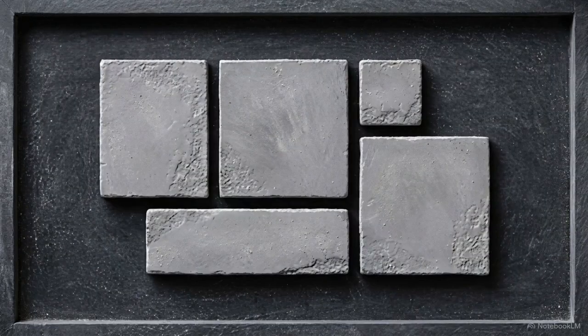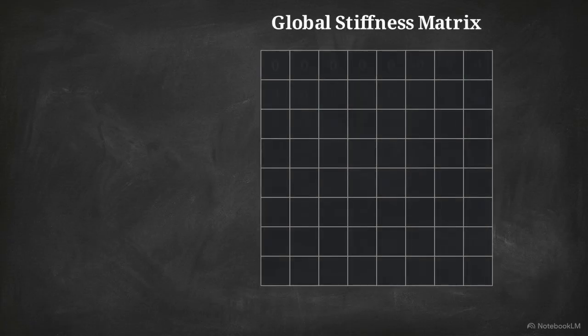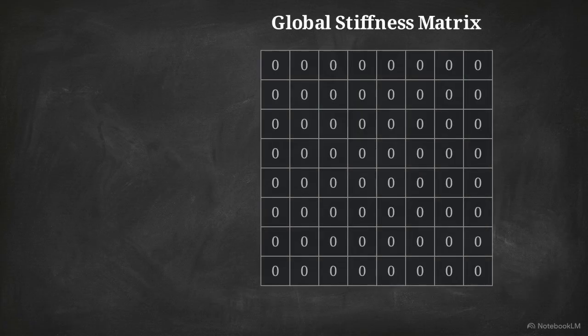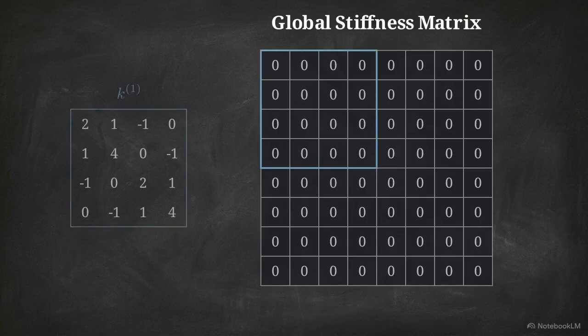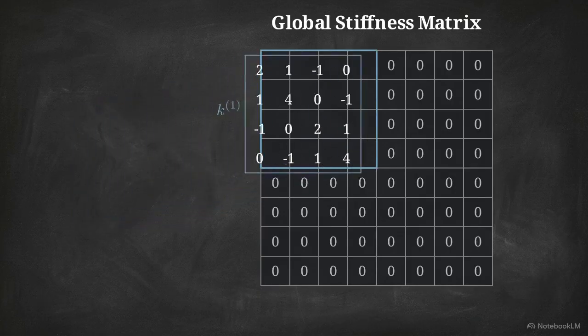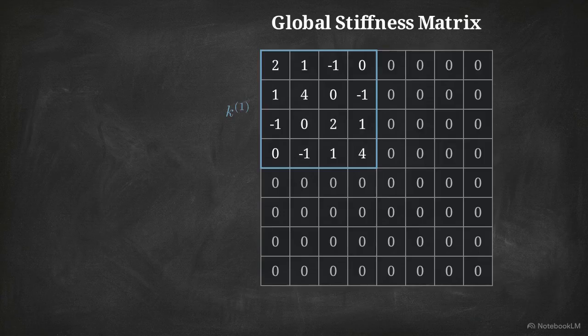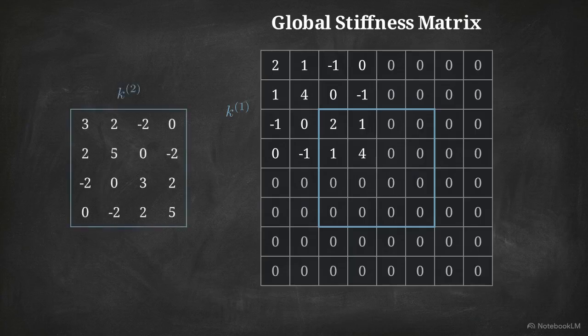Now we move to the global stiffness matrix. To save system memory, pre-allocate the space for it by setting up a zero matrix framework matched to your total nodes. We will populate those zeros using a standard for loop, which systematically iterates through each localized element and plots its matrix into the larger framework. This grid visualizes the mapping process.